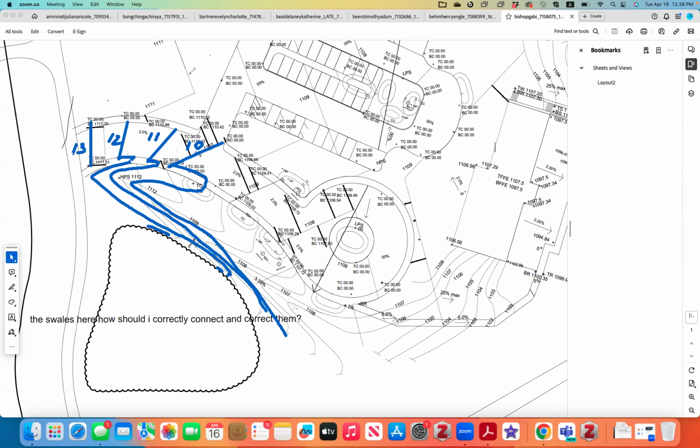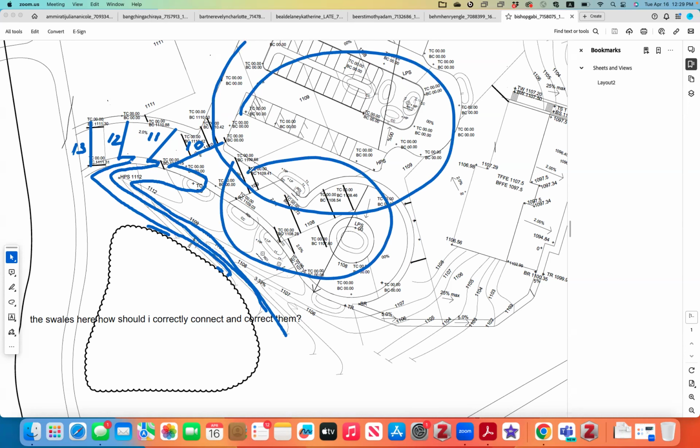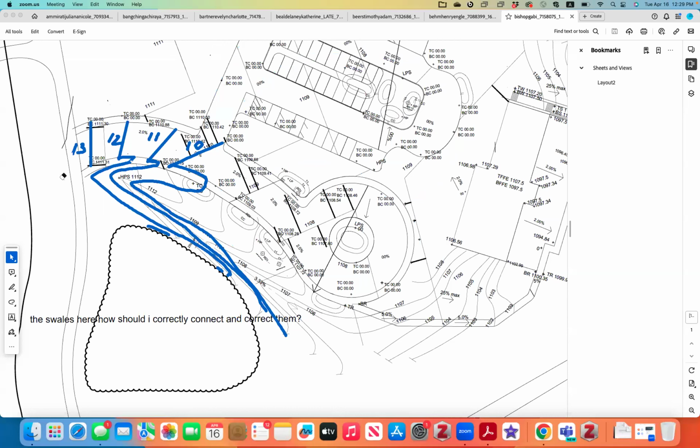With the 12, the slope of that entrance driveway, that's okay. Your entrance drive here can be steep. It's important for it to not be steep for this portion, and for that portion. So it is okay for it to go up to 14%, which is acceptable. So you're fine here with a steeper entry drive. Otherwise, you won't have enough space, right? If you want to, you can keep pushing it, but I think it's okay not to keep pushing it into the neighboring land. But you do need to change all these contours, all right?